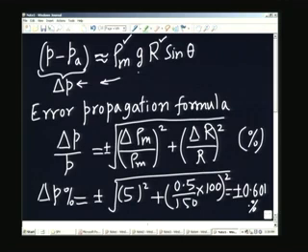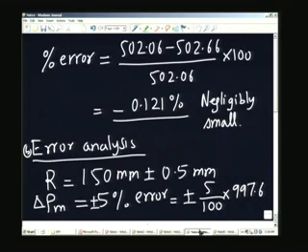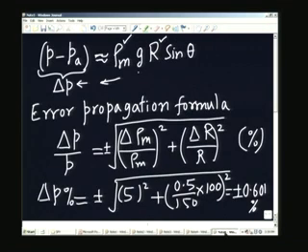Let me just go back. This is 0.5%. So, let me just correct it, not 5%. Actually, it is 0.5 by 100 into 9. So, the point I was making at that time was, with respect to 0.5%. I should have said that 0.5% itself may be too big to expect in this particular case. Therefore, the pressure is subject to an error of 0.6% because of the uncertainty in the density and the uncertainty in the measured value of R.